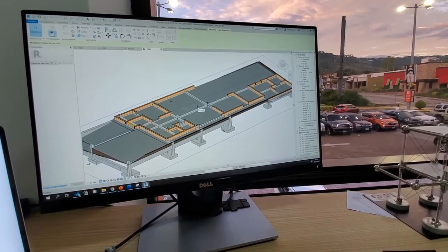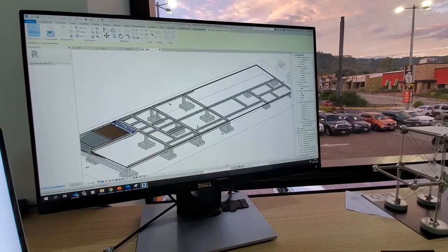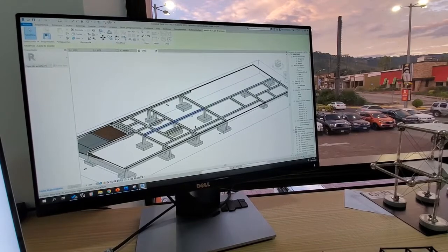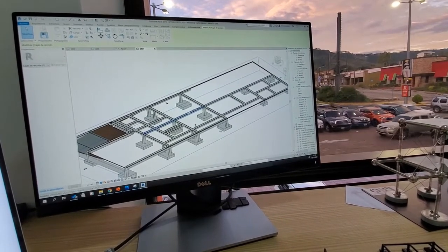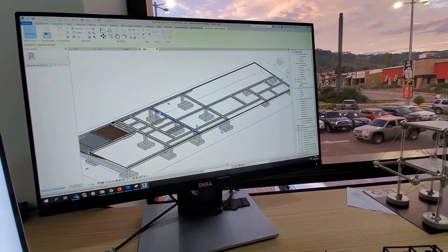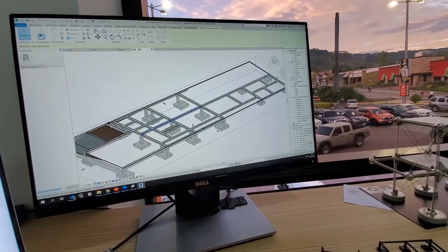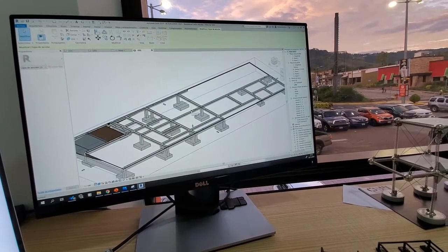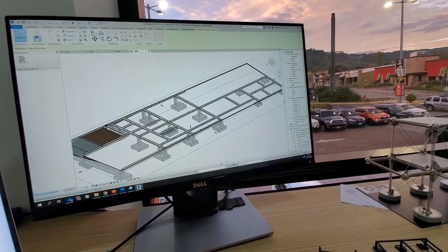The footing system for this house specifically is composed of isolated footings with some tensor beams, which in Spanish are called solera, and the function of this kind of beam is to connect the different isolated footings for our house. This is the footing system.